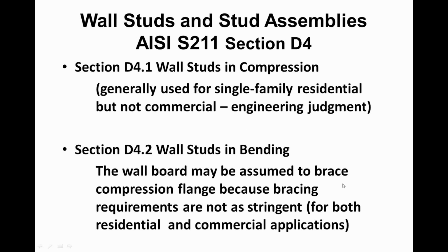In fact, in S213, AISI S213, which is the lateral standard, there are values for shear walls using gypsum. So even in a lateral system for my overall structural stability, there are gypsum values out there if I wanted to use them.